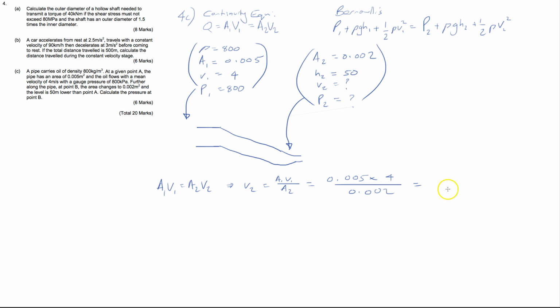That's convenient. Picked up a few marks there straight away. And that makes sense. You squeeze the end of a pipe and the velocity increases to compensate for the mass flow. Good. Let's stick it into this beast.